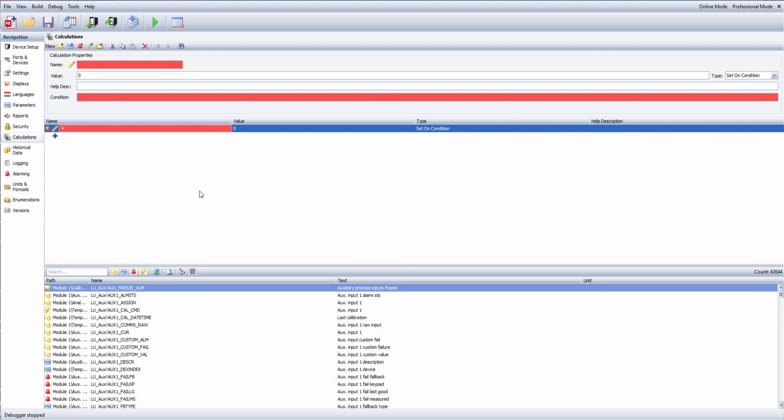write to. Now, all of the FlowX process inputs, temperature, pressure, density, you'll see that on the drop-down selections, you have selections for things like communications, for custom, for analogs, and so forth. We're going to use the custom. And what we're going to do is there's a tag on each one of these process values that has the beginning of the tag name, but then the end of it is custom value. So I use custom underscore val.